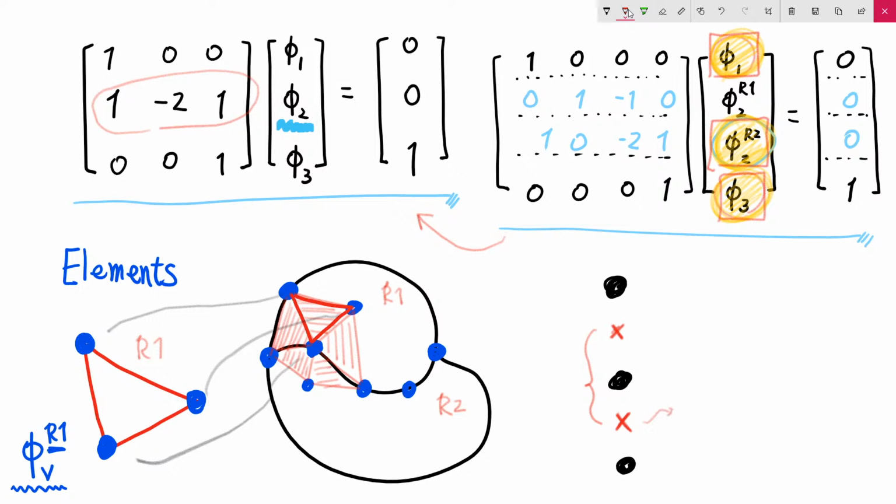So flux means that epsilon silicon d phi over dx at this point, and epsilon oxide d phi over dx at this point. And if you calculated this one, in order to make everything localized, then you just consider one single edge first, and you move to the next edge next.